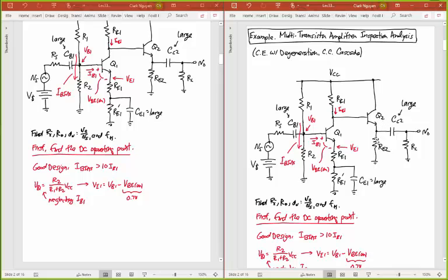All right, so I've got that voltage drop, which means now I can get this current. The current flowing through this, I really want IC1 up here. And let me write IC1 a bit nicer than I did there. So I want that IC1. And that IC1 I can get pretty much by just getting the IE1. Because if I assume that beta is large, then alpha is going to be pretty much 1. And so IE1 is basically going to be equal to IC1.